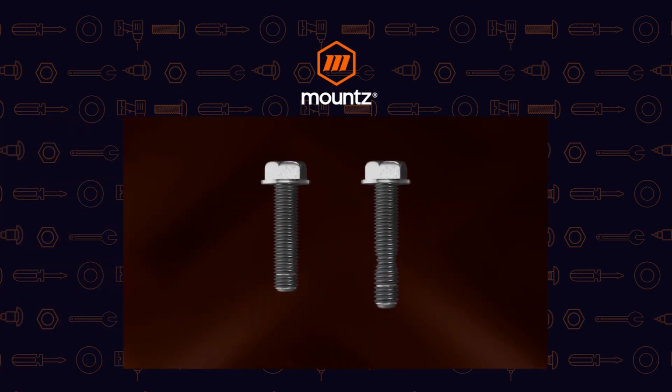And so in this example, you see two fasteners where one is able to return to its original size. The one on the right there is a little bit longer because it has been deformed and it will no longer return back to its original size. It has been moved past the yield point for that particular fastener.